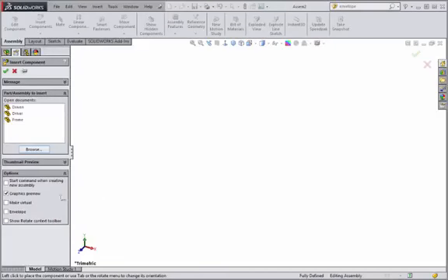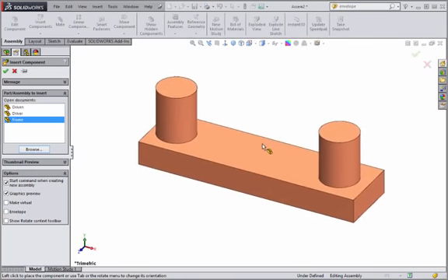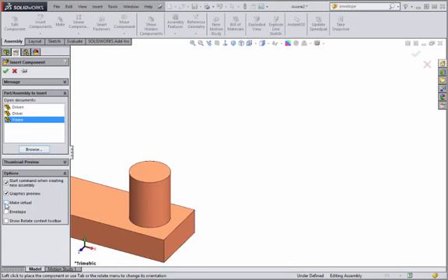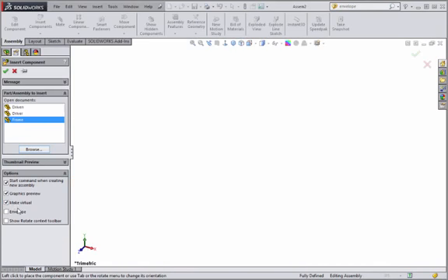Note that under the Options pane, we can enable the Start of the Insert Component command whenever we create a new assembly document. With the Graphics Preview option checked, we can see a preview of the selected document in the Graphics area as well. Make Virtual makes the component you are inserting virtual, which breaks the link to the external component file and stores the component definition inside the assembly file itself. Checking Envelope inserts the component as a special type of component, mainly used for reference purposes. As such, the component will not be reflected in any assembly bill of materials.